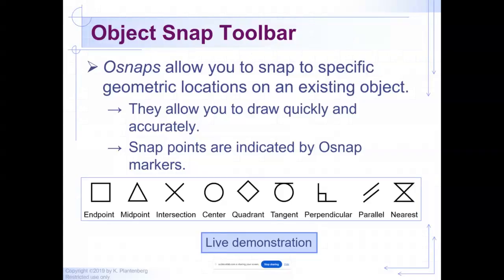I don't use it because I like things to be accurate. If you turn that on and it doesn't find the midpoint, it finds nearest to the midpoint, well, it's not exact. So then something might be off on your drawing. Like I use endpoint and midpoint. Midpoint is not a default turn on, so I turn it on.